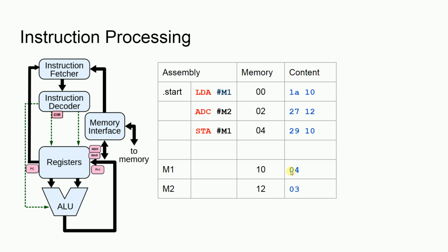What can happen sometimes is if this had got to be too big, so it went to, say, 270, it's too big for 1 byte, the accumulator might throw an error and say overflow. And this overflow might say branch on overflow, which says change the memory address. So you could get instructions that will change the program counter. So that's the sorts of things that a processor will do.